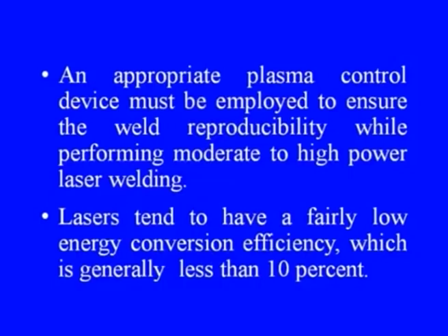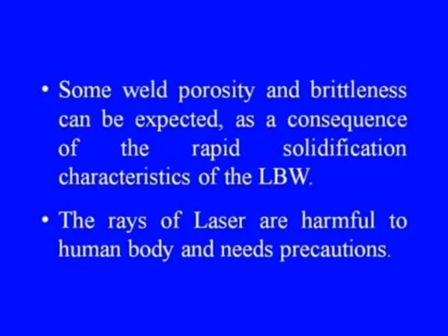Lasers tend to have a fairly low energy conversion efficiency, which is generally less than 10%. So, this is a point of concern as far as the economics of the process is concerned. Some weld porosity and brittleness can be expected as a consequence of the rapid solidification characteristics of laser beam welding. The rays of laser are harmful to the human body and need precautions.